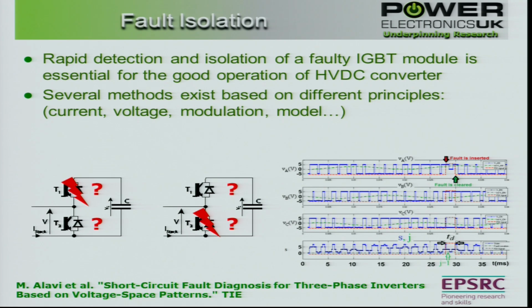Because you could maybe do something relatively simple, like look at the overall voltage you expect to get across a bunch of cells and see whether that's equal to an integer number of cell voltages. And if it's not, then you must probably be dropping a lot of voltage across a particular device. And consequently, this is something that you might be able to use to react very quickly if you detect a device is starting to fail.